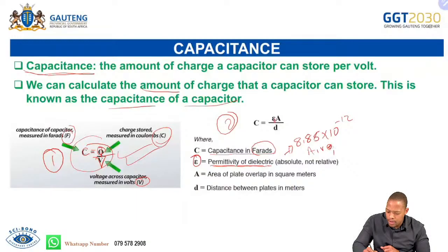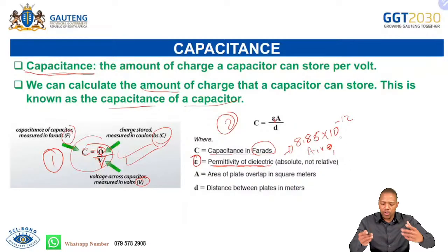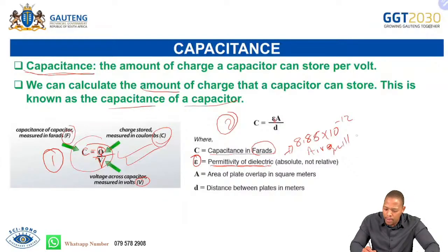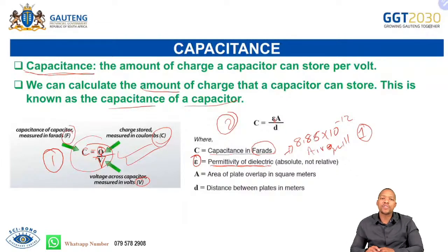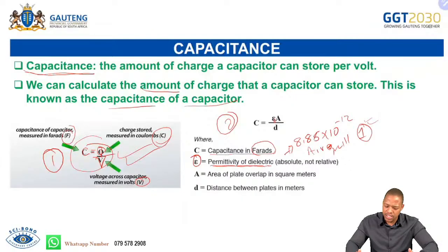Okay, I hope. And then, most dielectrics such as air will have a relative permittivity of what? Of 1. I just feel like I should mention this. There's a relative permittivity for each dielectric material that could be used, but other dielectric materials will have one that is not 1. But if they say it's air, or they say there's a vacuum in between, or they say nothing of the dielectric material that is there, you can always assume that the relative permittivity will be 1.